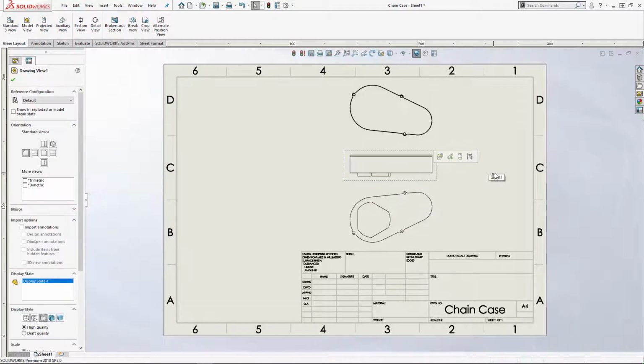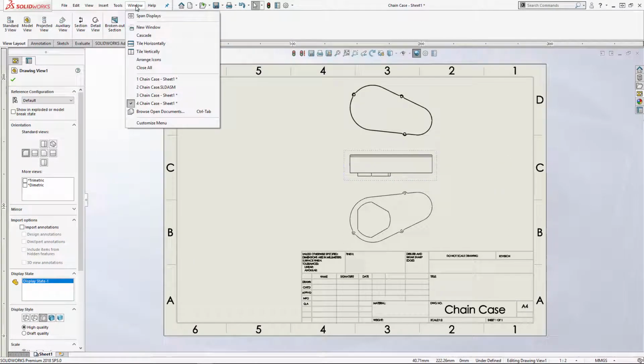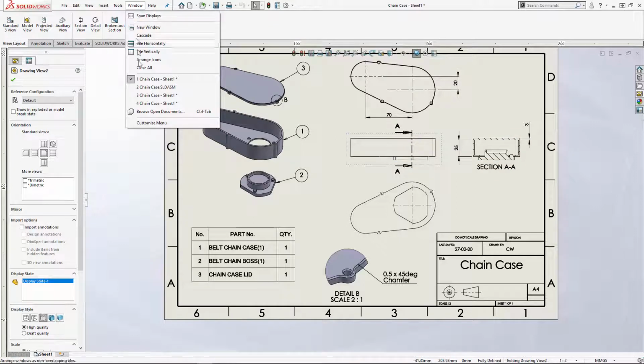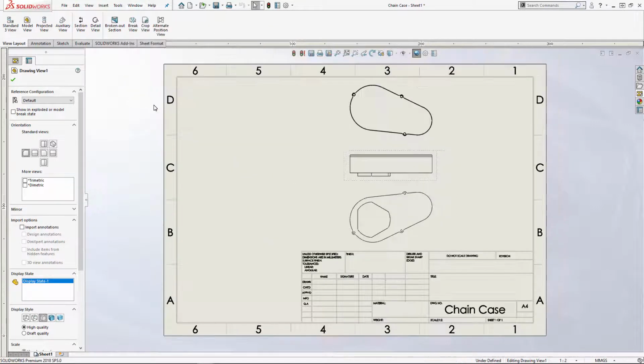So let's put this section view over here. If we go back to the reference that we're working from, we've got a vertical section line there. The section line itself chops through the part. It has arrows on it indicating the view direction, that you're viewing the sliced portion, or the sectioned portion. So let's insert that into our sheet now.